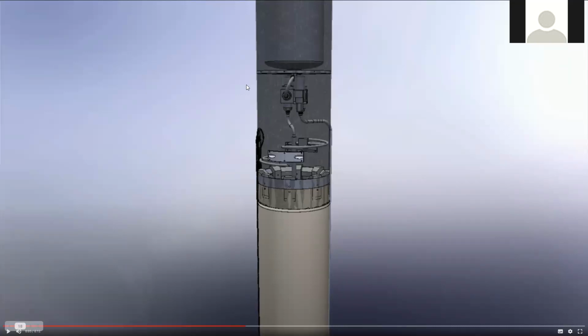The rockets that I know about use the aerodynamic heating to sometimes boil off more oxygen and then do autogenous pressurization. That works better if you're using something like nitrous oxide, which can actually self-pressurize, and then you don't need to carry a pressurizing gas with you. But using propellants that allow you to take advantage of some of those things,